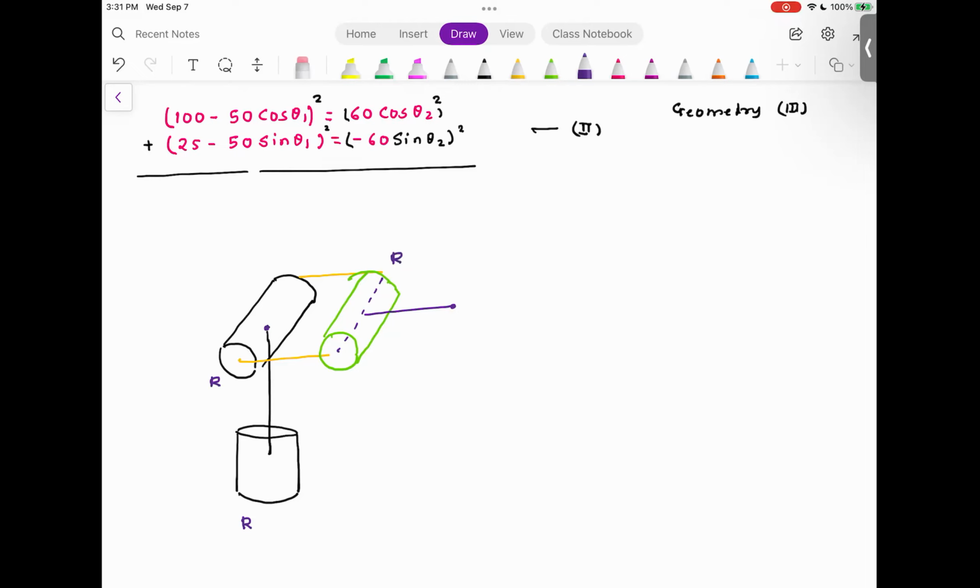The first revolute joint is perpendicular to the second revolute joint. The second revolute joint is parallel to the third revolute joint. So this is an R type of robot. Everyone understood this? Now I need to set up the coordinate system. So the Z axis must pass through the joint.